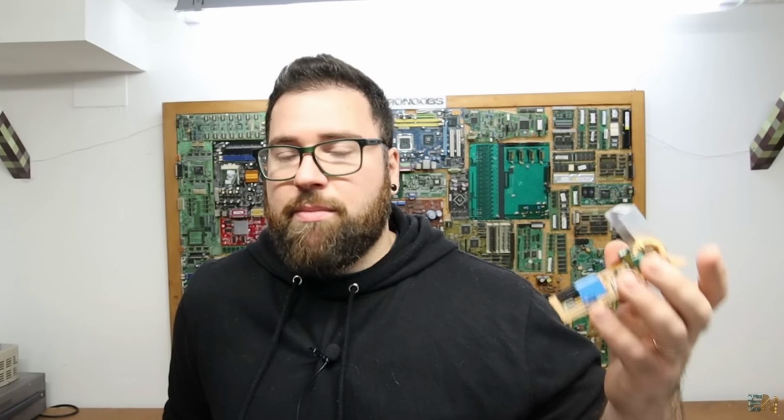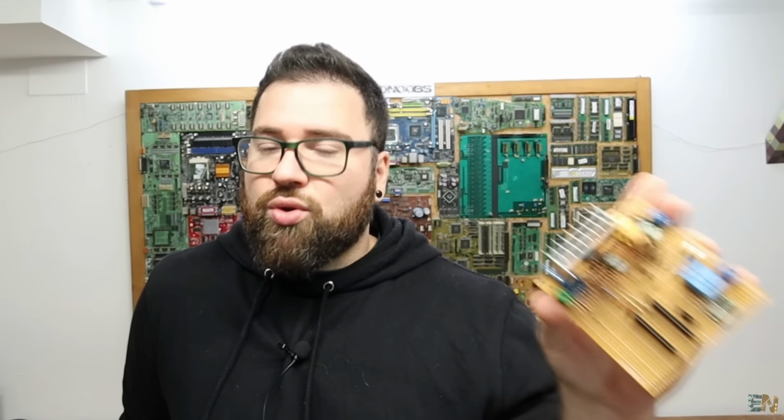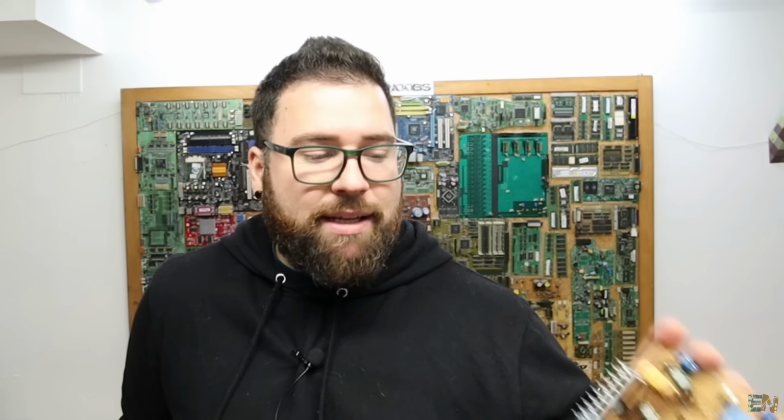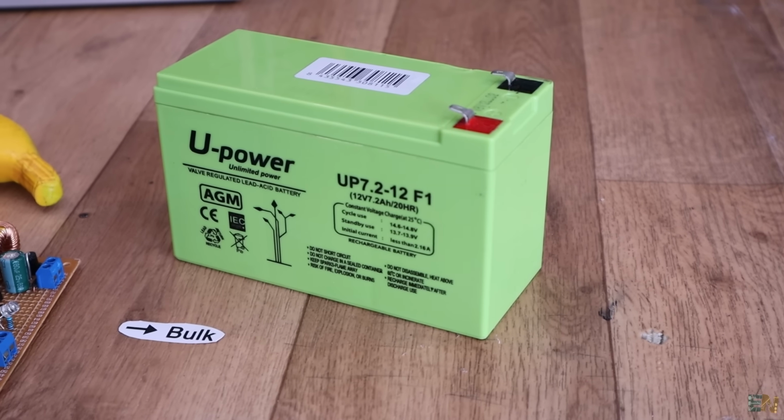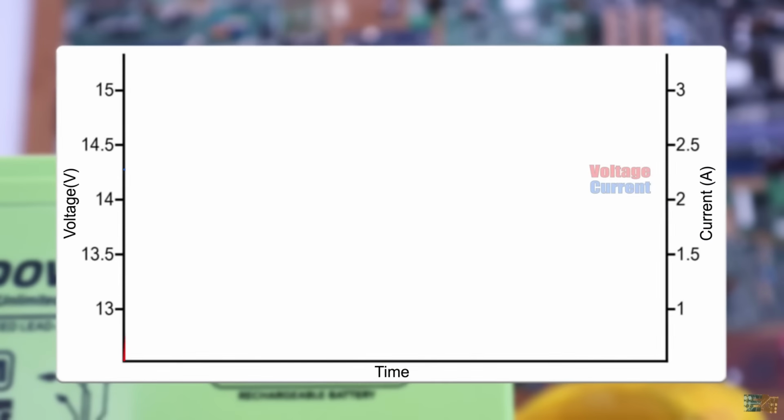My project was just a prototype. I wanted to show how MPPT works. That's why I've made this PCB. Was it perfect? No. Was it a real MPPT? No. That's because more than half of the time this controller was working in PWM mode, because I made this to work only with lead acid batteries, which is something like this, a battery from a car, for example. And this will have a graph like I can show here on the screen.